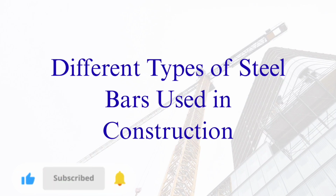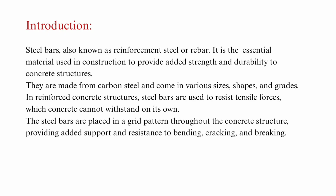So let's get started. Steel bars are also known as reinforcement steel or rebar. It is an essential material used in construction to provide added strength and durability to concrete structures. They are made from carbon steel and come in various sizes, shapes and grades. In reinforced concrete structures, steel bars are used to resist tensile forces which concrete cannot withstand on its own, because we know that concrete is strong in compression only and it is very weak in tension. So steel bars are used to provide reinforcement in tension as well as in compression.